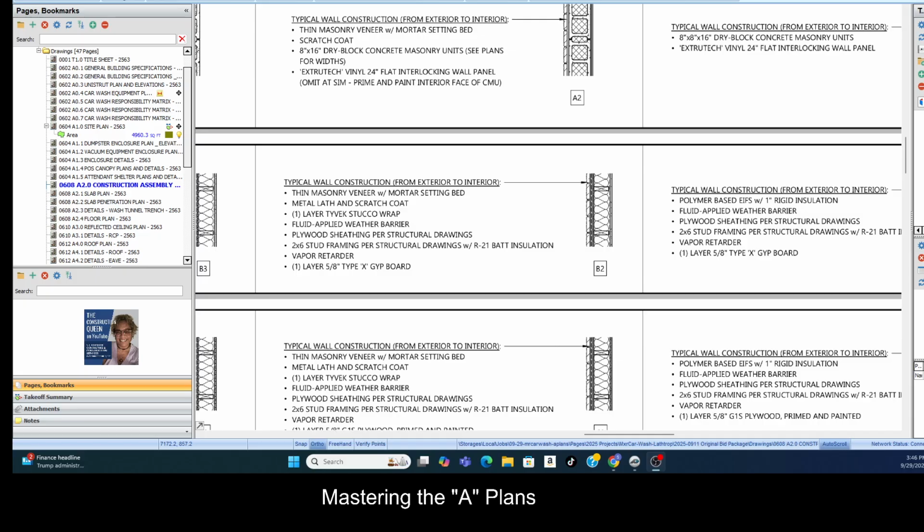So when we do our framing estimate for each type of wall, so for B2, there would be a line item. And it really depends. The framer may not be doing the brick veneer, but he's going to exclude that. And the framer may also not be doing the plywood because those are considered other scopes. Usually the framer frames the walls. They don't do the plywood. They don't do any of the rough carpentry like the plywood on the roof or anything like that. More of that we see in the structural set. So it really depends.